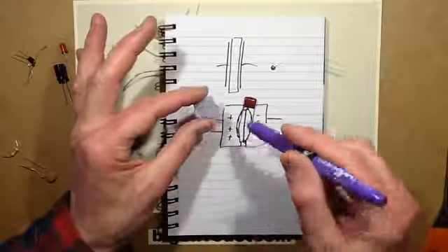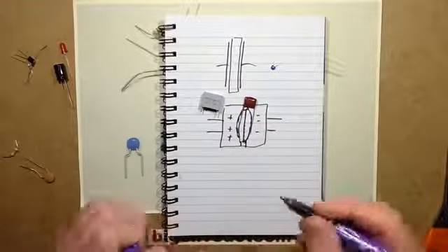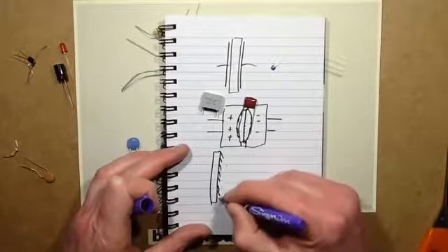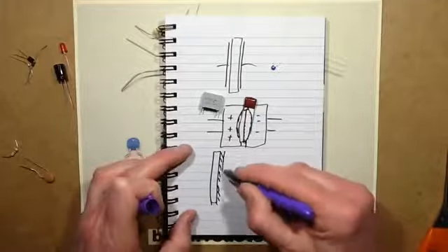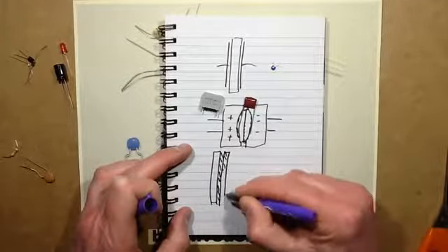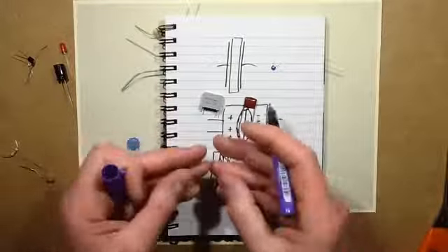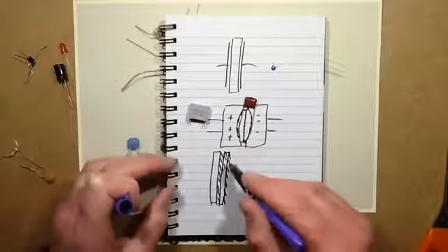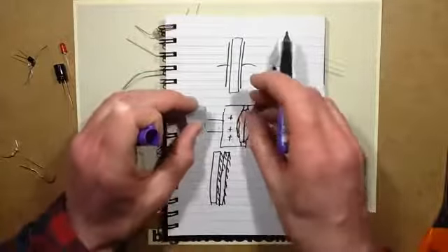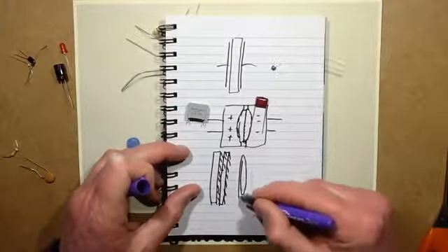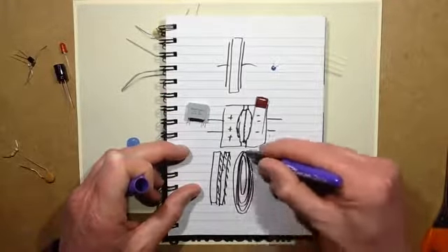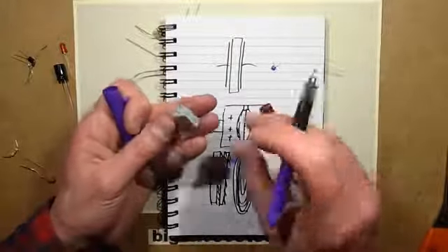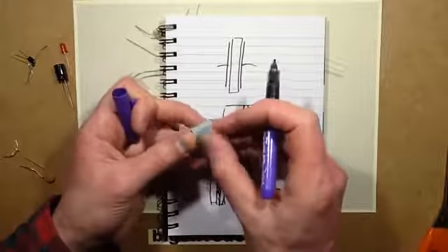To make this type of capacitor, these are metallized film capacitors, and it's a film that's metallized on one side. They take two strips of it and they basically sandwich them together. The plastic aspect of it is the insulator, and the metallization is the electrode. And to fit a lot in a small area, they then actually just spiral. They take a big long strip and they spiral it round into a small area, and that's what creates the larger area. And the thickness of the plastic film itself will determine the voltage rating.